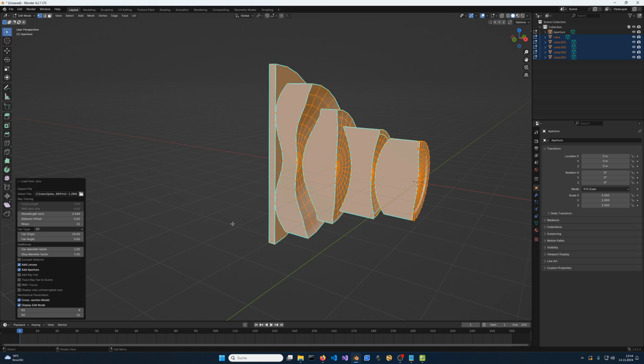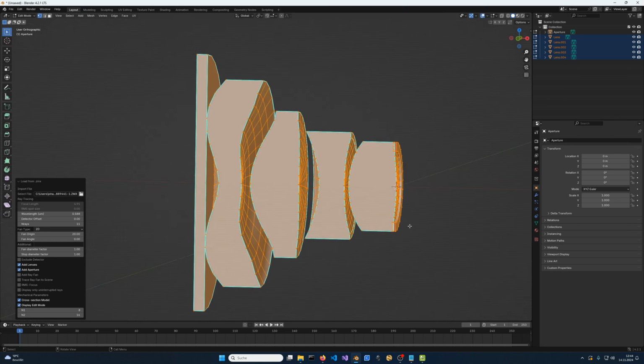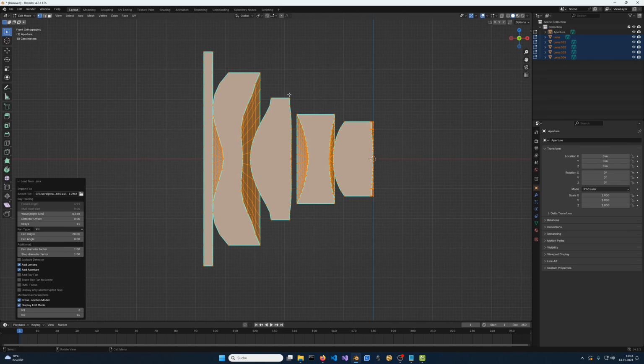This is now composed of 4 lens elements and 1 flat filter, and still the aperture is at the front of the first surface. Here we can see that the 4th lens really deviates from spherical shape. The back 2 surfaces are very complex, and there is an inversion in the direction, so you can no longer classify it explicitly as either concave or convex. The polynomial terms really dominate here.